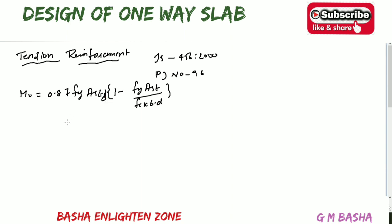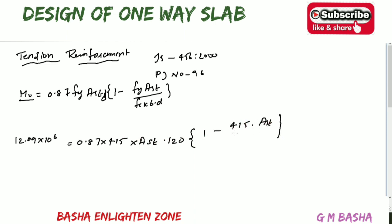Okay. So we already know the value of Mu, that is 12.09 into 10 to the power of 6, and again all the values. Fy will be 415, and here the unknown is the area of the steel, and we know the effective depth also, which is 120, and again 1 minus this 415 into the unknown area of the steel, and again fck 20. Here we are considering this b value as 1 meter. Already I told you, that is taken as 1000 in terms of mm, and again 120.